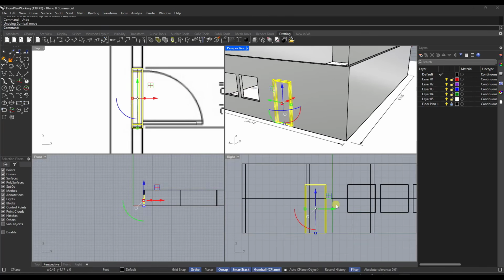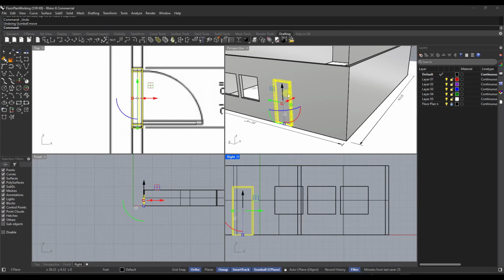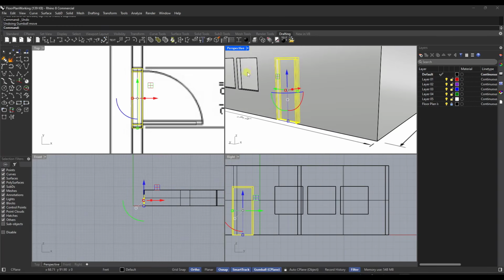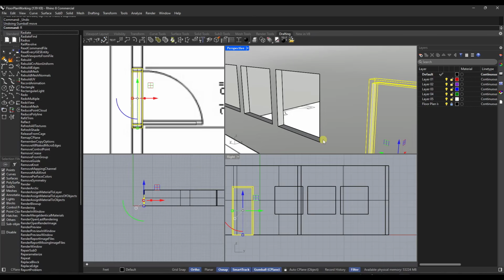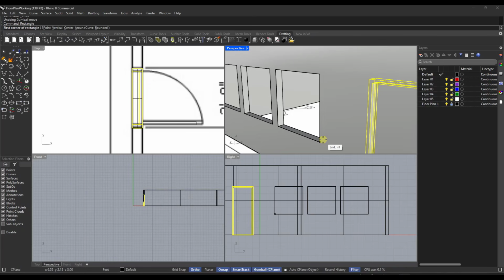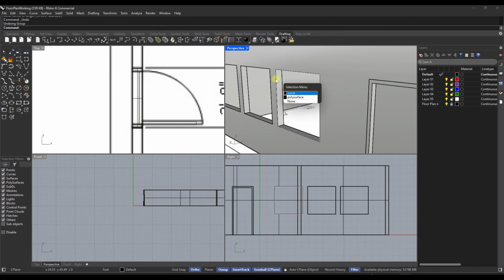And so let's do the same thing with our windows. So what I'm going to do is start by drawing the outside of our frame. So we'll type in rectangle, find this corner point, and again you can see if I mouse over this point right here, and remember that our curves are still here for our windows, so we can just do that same thing.